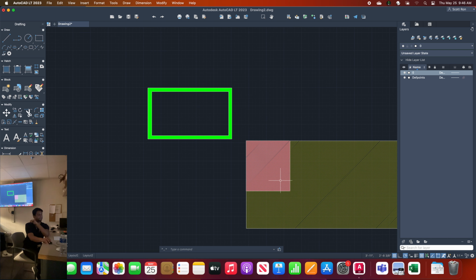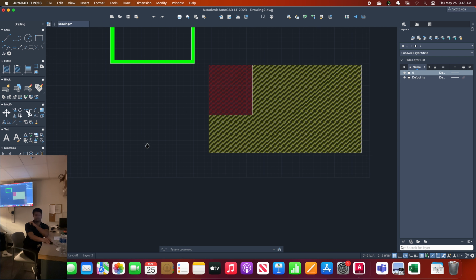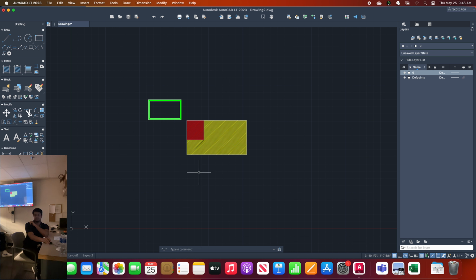Done. Should we make separate layers when it comes to hatching? Yes. Just layers just for the hatches? Yes. In fact, if there are hatches that mean different things, then multiple layers, whatever they mean. Okay? Simple.